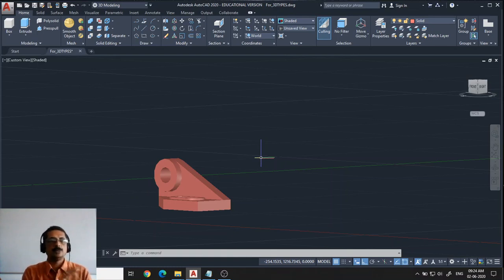There are a few commands in which we can move in any plane. Like now for the line command, you can start from any point to draw to any point. That is, you can draw it in 3D space. Similarly, we have 3D poly, an equivalent of polyline, which we can draw in different planes, right? But for all other objects, like circle, arc, or rectangle, you can draw it only in one plane.